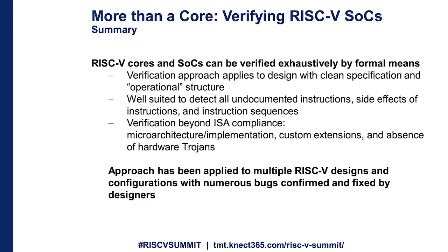So it's well suited to detect all undocumented instructions, side effects of instructions, and instruction sequences, reaching unbounded proofs, verification beyond ISA compliance. So it's not only about ISA compliance, but takes into account the microarchitecture details. We are not yet there at supporting the custom extensions, but we are working in that direction to automate it and to make it easier to deploy.